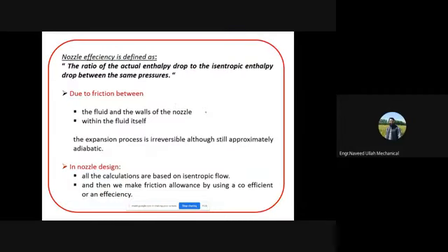then after that, let me summarize under and over expansion cases for the convergent nozzle and convergent divergent nozzle. If the back pressure value is less than the critical pressure, we have the under expanded case, and if the back pressure value is greater than the critical pressure or the design value, that is over expansion. And in between these two we have actually the right amount of expansion.